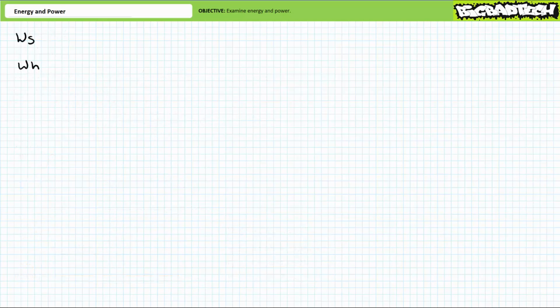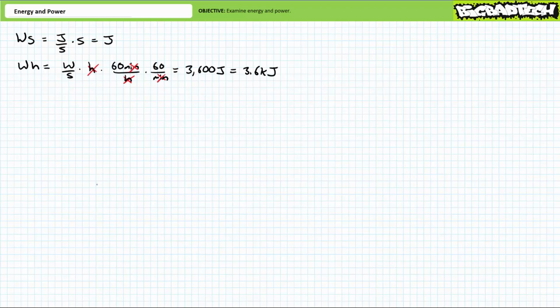Moving on. Returning to our discussion of units employed when quantifying energy, the kilowatt hour makes a handy unit for most small-scale residential applications. However, if the application is smaller in nature, like a portable electronics device or sometimes batteries, you might alternatively see units of energy represented in watt seconds or watt hours. The watt second is simply a stupid way of writing a joule, because 1 watt times 1 second is 1 joule per second times a second, which yields joules. And a watt hour is a larger packet of joules. If 1 hour equals 3,600 seconds, a watt hour is 3,600 joules, or more appropriately, 3.6 kilojoules.